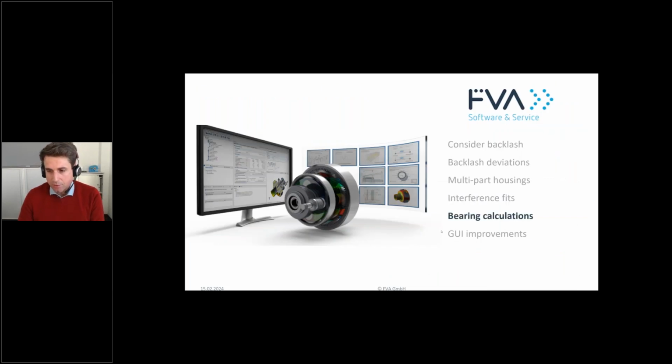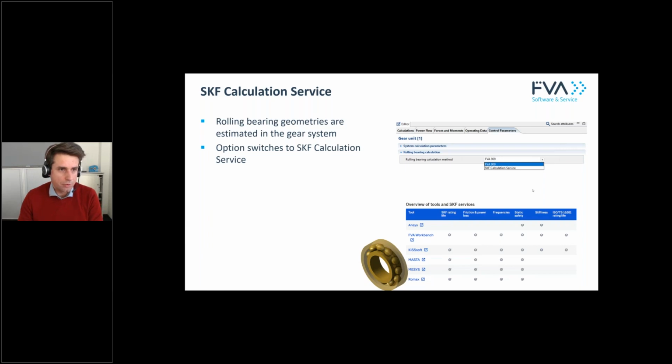Let's also talk a little bit about bearing calculation, and I would like to talk about the SKF calculation service. We're using the SKF calculation service for a couple of releases, and we used to support the stiffness simulation and the service rating life simulation according to ISO TS 16281. But we now added also the SKF rating life, the friction and power loss simulation, and also the rolling frequencies and static safeties.